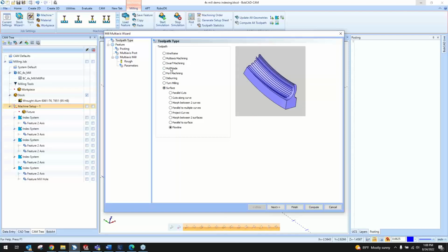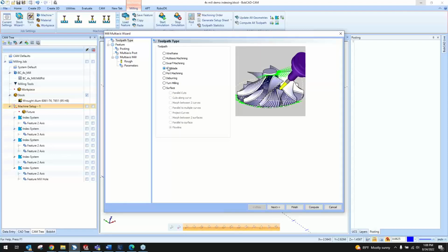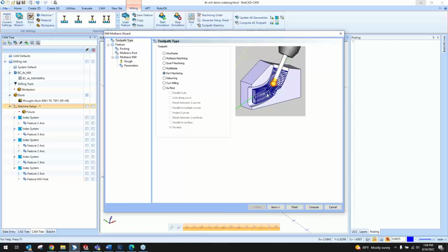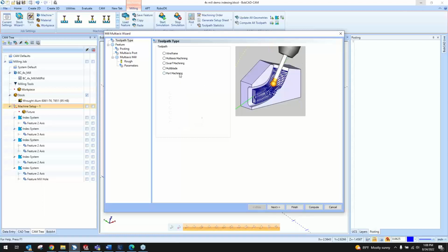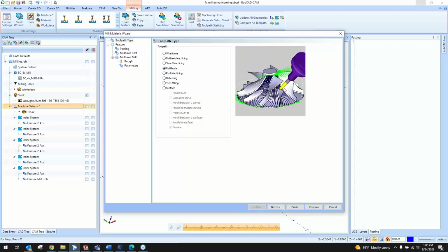And then now we have added the 5-axis premium. 5-axis Pro is swarf machining, and then 5-axis premium toolpaths that we've added now are multi-blade for impellers, port machining, and we did add deburring for the 4-axis premium now as well. So these three are newer milling operations here.